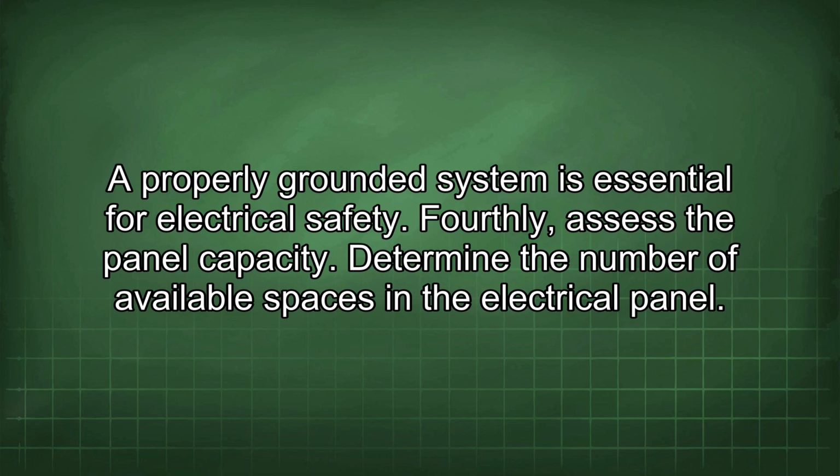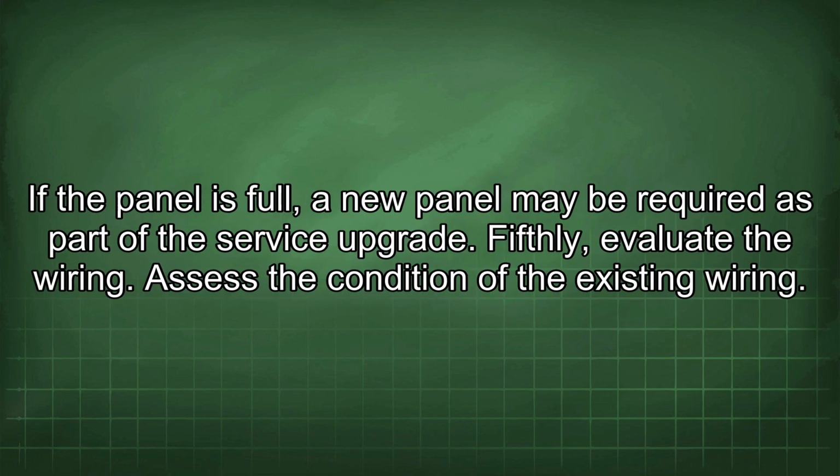Fourthly, assess the panel capacity. Determine the number of available spaces in the electrical panel. If the panel is full, a new panel may be required as part of the service upgrade.